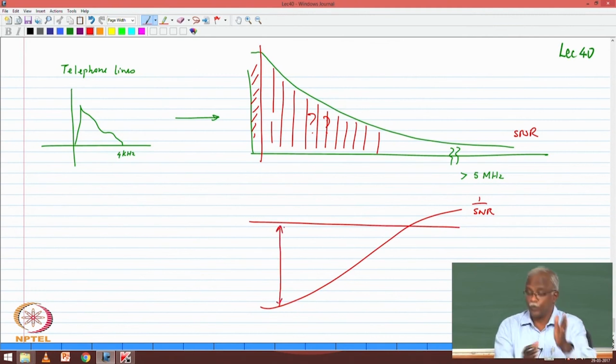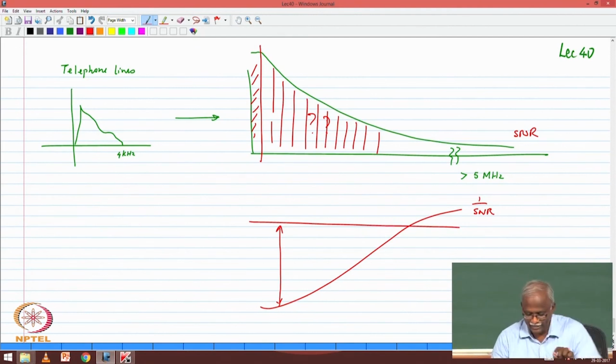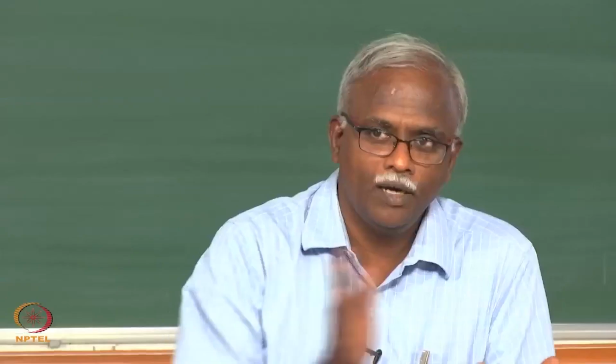So you can do 64 QAM on the first carrier and then BPSK on the last carrier, with appropriate power allocation. And this is what gets you many, many megabits per second on a telephone line when all you were using it for was 64 kilobits per second. Okay? So again, water filling, one of the most powerful concepts in capacity. We have water filling over time is what we were trying to solve, but it helps us address the broader issue of what do you do with wideband signals which have frequency selective fading. No problem, I do water filling across the different frequencies, choosing to do no transmission on some carriers.